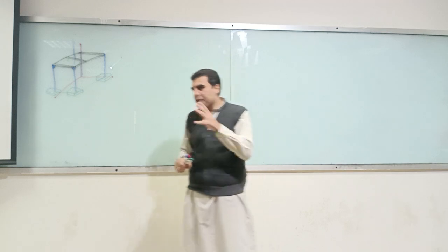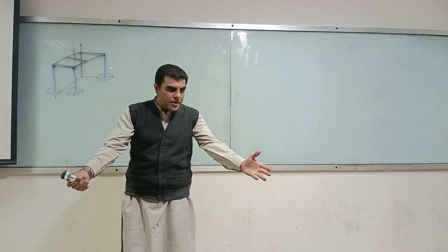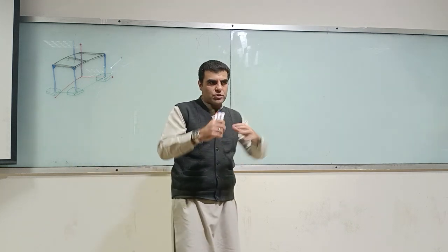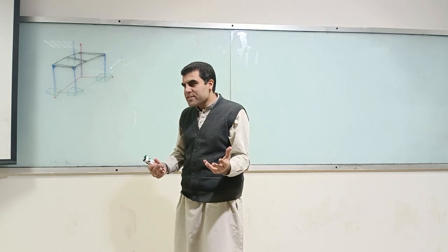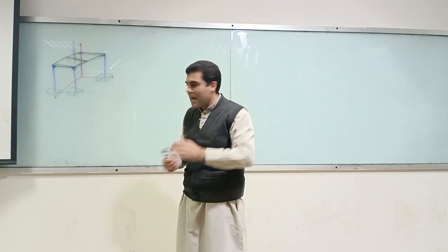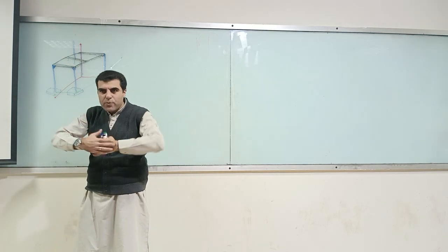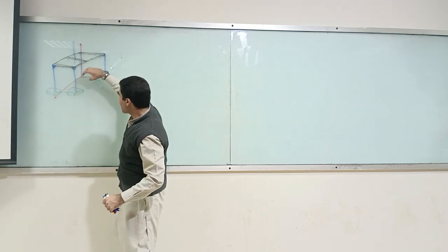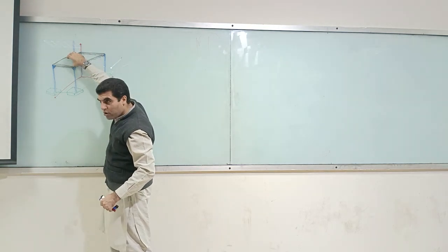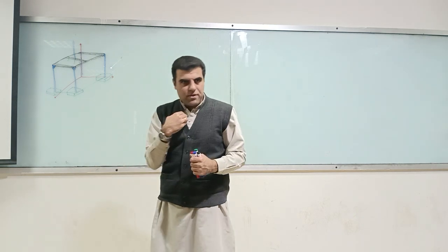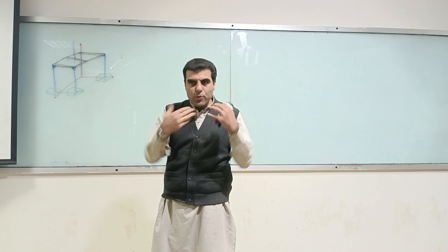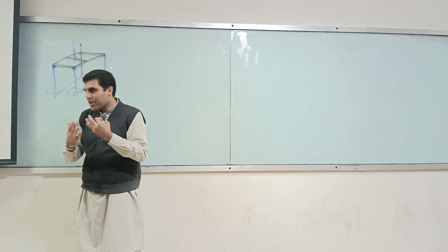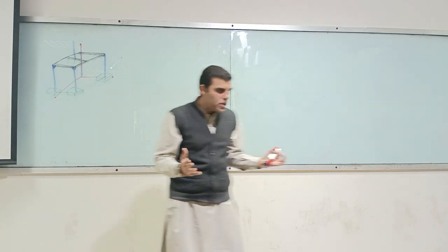most of the loads which are applied onto structures are concentrated loads. Your desks, your chairs, you guys walking, they are all concentrated loads. But if their number increases, then instead of considering them as concentrated loads applied on this structure, we assume that they are distributed. Imagine you are sitting over here on this level, and your load on this structure is actually a concentrated load. But to make our life easier, we assume that your load is spread out, in other words, that load is uniformly distributed. So how do I work out your load? How do I work out my load?